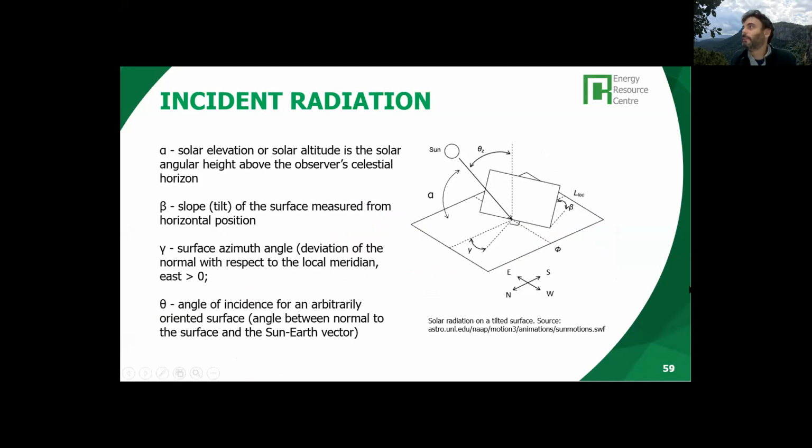So basically when we have a solar panel, we can consider in the design 3 different angles. This one here is the azimuth. This one here is the solar elevation, the alpha. This is changing depending on the seasons. When it is winter time, for you now it is summer, your sun is quite high. Your sun at noon will get a maximum solar elevation or solar altitude.